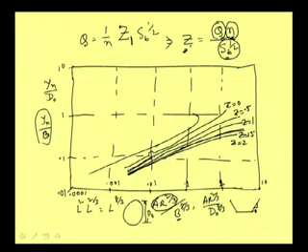Then we can calculate the Z1 section factor, the Z1 value of that particular flow. And for that Z1 value, now we know the side slope. Suppose it is a rectangular channel, then we first see in this graph, and we know the b value. So, we can have Z divided by b to the power 8 by 3, and we will get that value here.